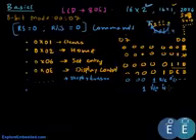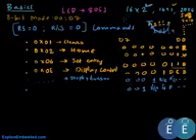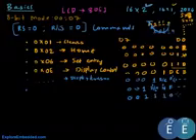Now the next is called the font. If it is 5x8 font, this would be 0, and if it is 5x10, this would be 1. And then this is don't care. So if we calculate this for our 16x2 display, this would be 001. Since for the first part we'll be using the 8-bit mode, it would be 1, and the number of lines is 2, so this will be 1, and we'll be using the default font size.